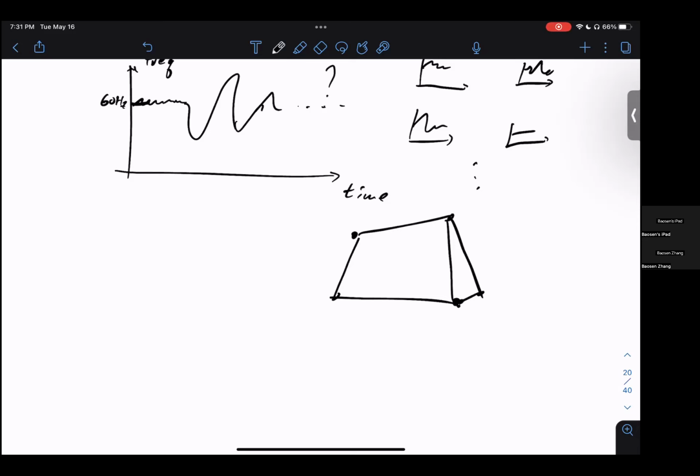This is a very challenging learning problem. The challenge comes from, one, real systems have more than 10,000 buses. So you have a picture with 10,000 pixels. Each pixel is actually a function. You're measuring this oscillation, and you get all these things together. I want you to decide in, let's say, 100 milliseconds, yes or no, whether the system is stable or not.